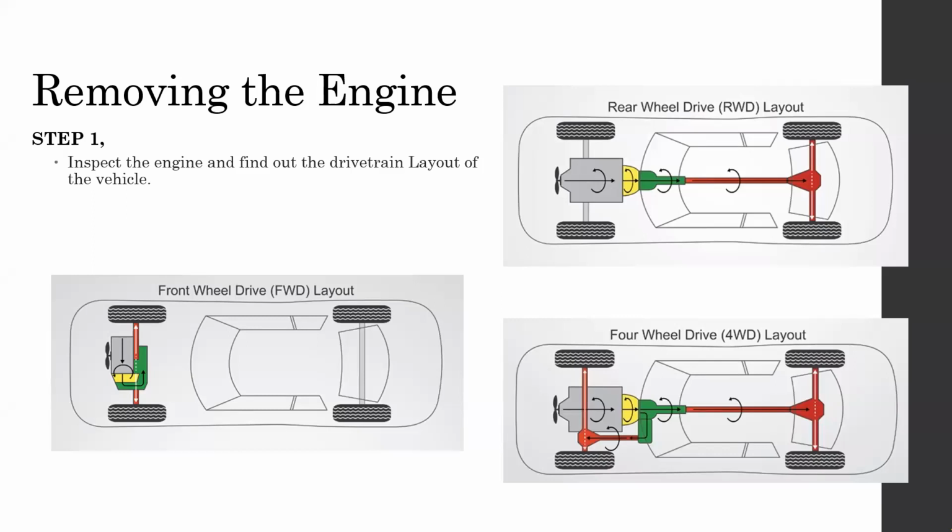In addition to this, the other one is the electronic fuel injection system of modern vehicles. They have a returnless type, where you have a fuel pump at the back of the vehicle or inside the fuel tank. It will deliver fuel through one line, but the return and pressure control are done inside the fuel tank. So it doesn't actually have a return line. You need to notice these things.